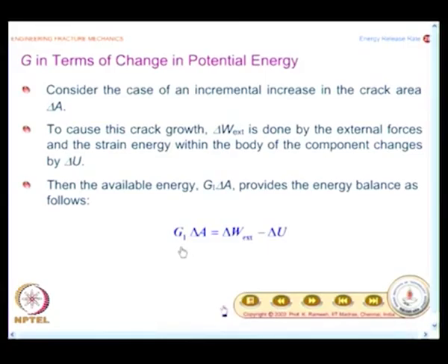And how are we justified in writing this energy balance? We are considering ideally brittle solids. There is no dissipation of energy. One form of energy turns into another form. And here again we look at the point when the crack is about to propagate. We are not looking at the instant after it has started propagating. We are writing only for that instant. This energy balance, what we have got, we would recast in a convenient fashion. See, in theory of elasticity, people have a definition of what is potential energy. We would try to recast this expression in such a fashion.